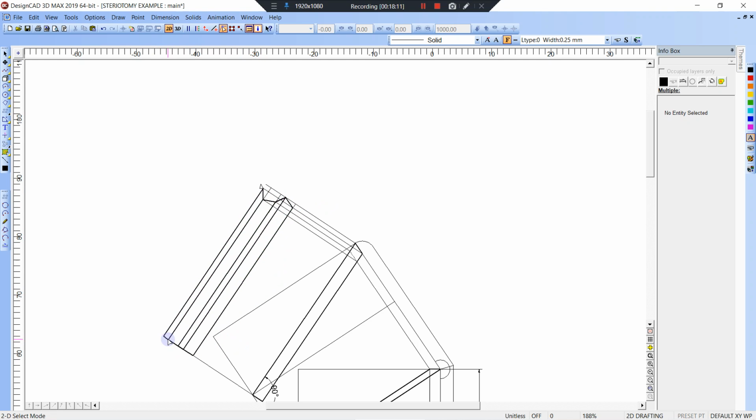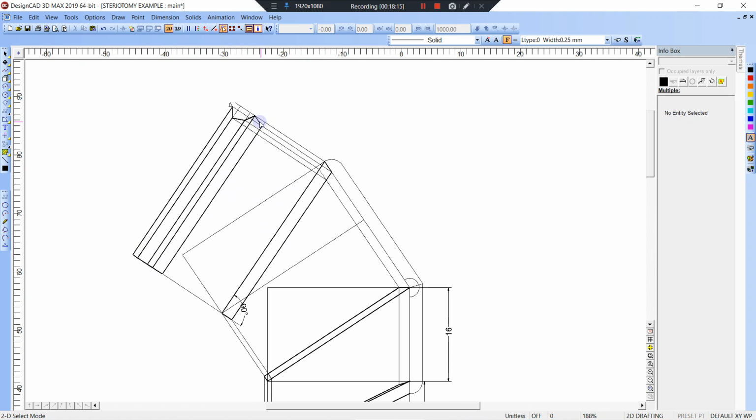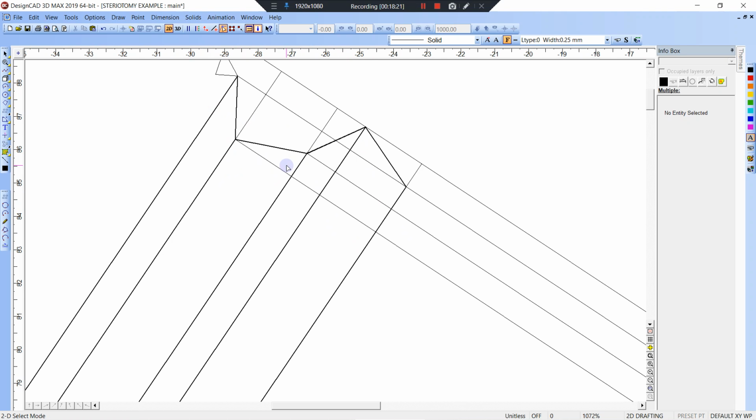And there's your pattern. That would be a pattern that would wrap around this. So that's your actual cheek cut right there, and that's your plumb cut. And if you look at that, what we said it was, I forget, Alt MA.